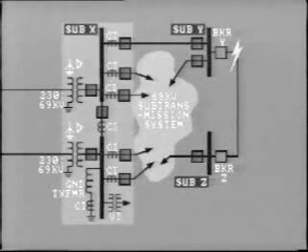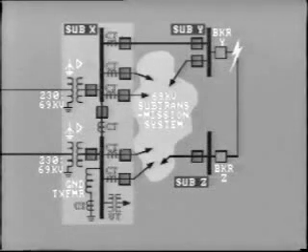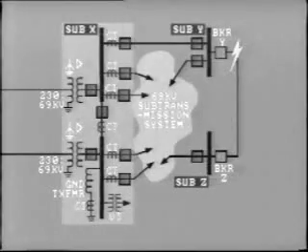This example has demonstrated 2 things. First, the nature of a fault can change during a disturbance, and in this case, the protection operated correctly to clear the fault. Secondly, our example showed that recording equipment located several buses away from the actual fault can still provide valuable information during a fault investigation. Let's now move on to our third case, an overtrip for a remote fault. This is a clear example of misoperation.